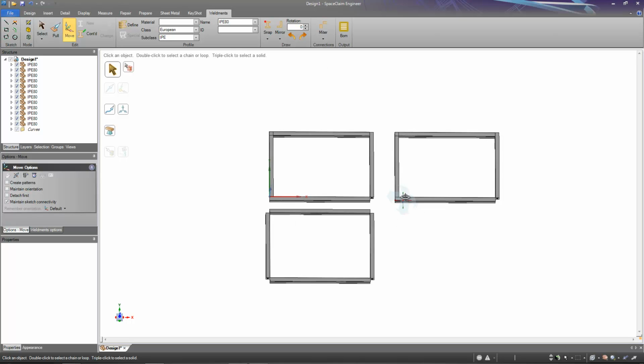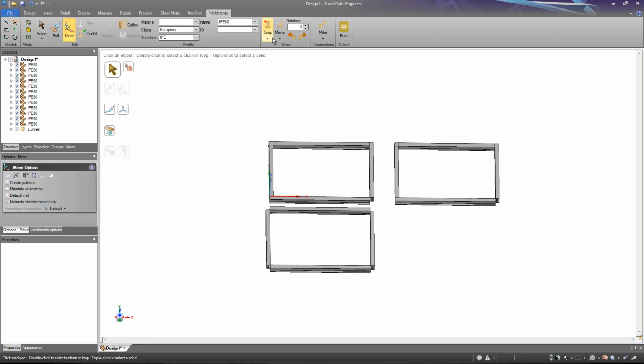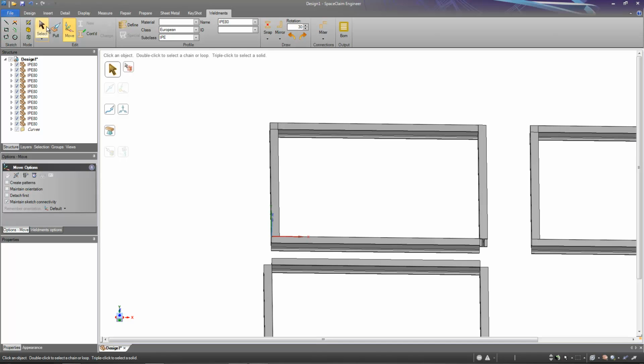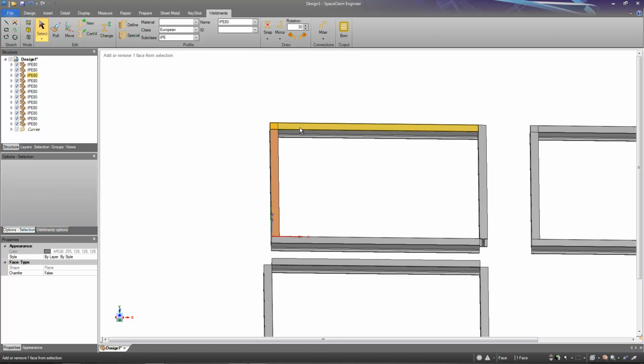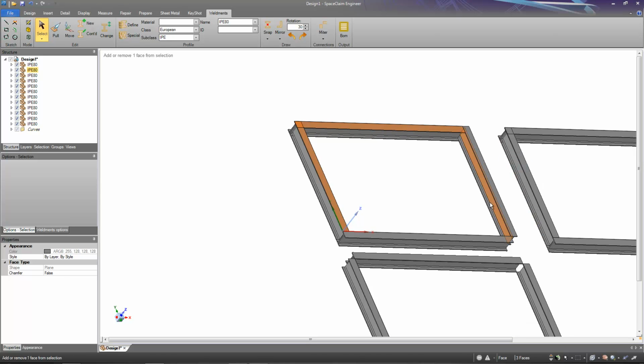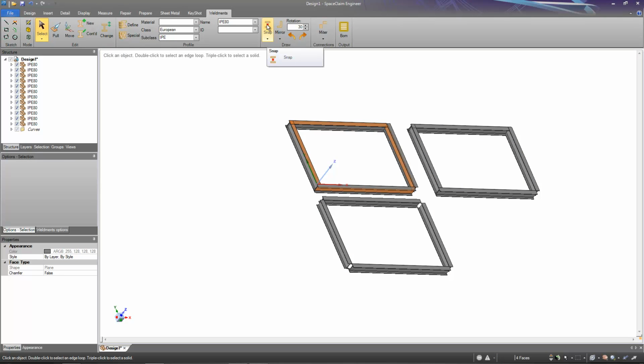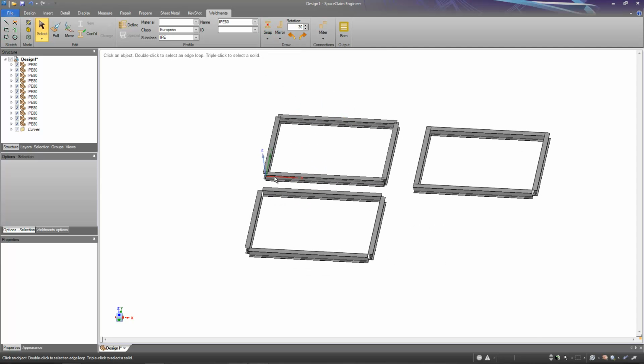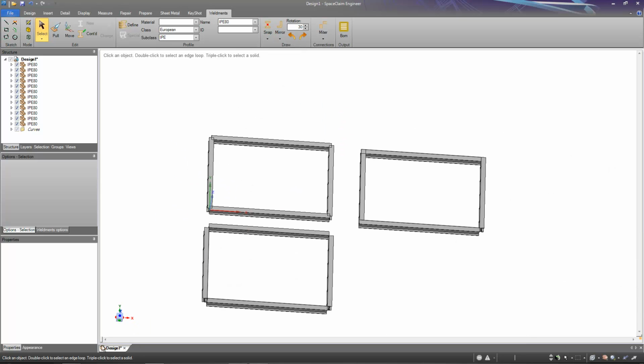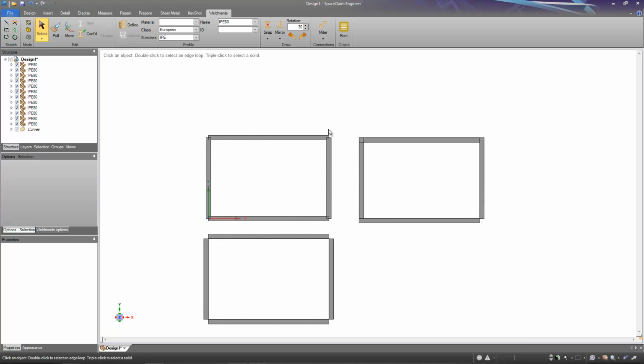Once you're finished here, you can start again editing snap points. For example, I will set my snap point to middle, and just for reference I will add a rotation of 30 degrees. If I then in select mode select a surface of a new profile, doesn't matter which, and click again on that snap button, not on the arrow but on the button, the snap position of those profiles has been changed. You can see the overview here, reference to there is not the same.